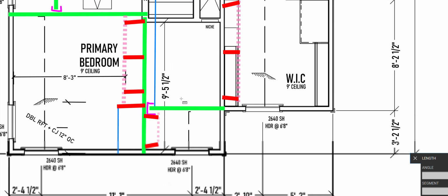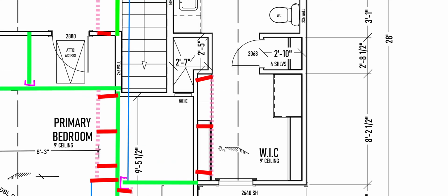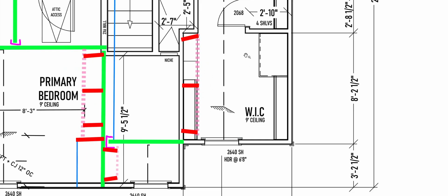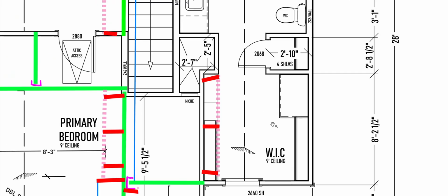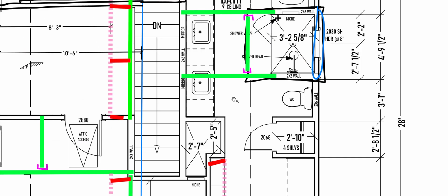And now the span from the ridge to the purlin is like 6 feet. So yeah, all my 2x6s are just fine here. So I'm adding effectively just a tiny, tiny bit of weight from the ceiling here. And that's going to lower my span, but I just dropped my span to like 6 or 7 feet. So I'm well within my allowable use here.